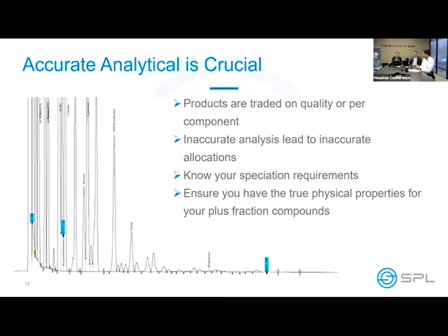What are we going to do with gas? Gas ordinarily goes to a hexane plus. What are we going to split that out? You usually do a theoretical split on your hexanes plus. The standard is 60-30-10, which was arbitrarily discovered, but actually works pretty darn good. Or are we going to do something more extended, a C9? What are you going to be using it for? You need to know what you need to have speciation-wise and what you need to have physical property-wise to feed this model to make it as accurate as possible.